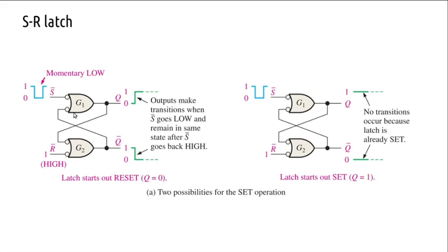This 1 reaches here as feedback. So this is going to be 0. The feedback coming here is Q bar, and this high 1 is going to give you a feedback of 0, and that is fed back here. So 1 or 1 NANDed with 0, that is going to give you an output of high. Q bar is going to be high, right?